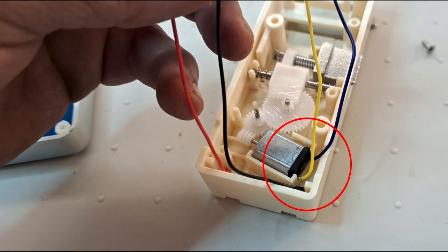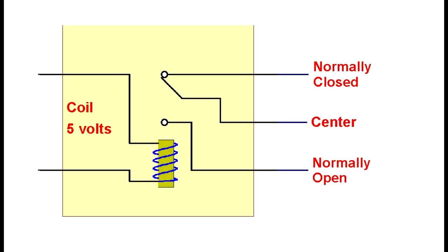The activation for the digital lock is the 2 wires leading to the original latch motor. It is rated for only 5 volts at about a quarter amp. This is nowhere near enough to activate the solenoid latch that will open the cache. You will therefore need a relay. In this case, 2 relays were used with the coils connected in parallel. I will talk about the purpose of the second relay later.